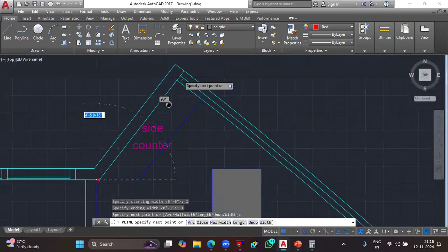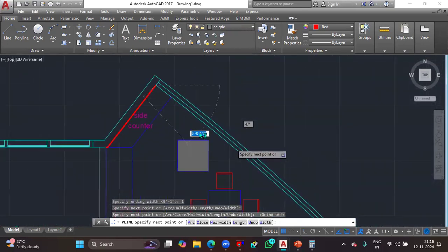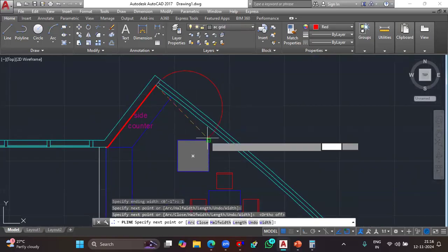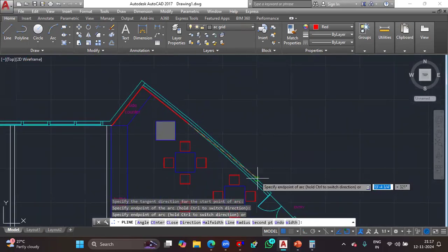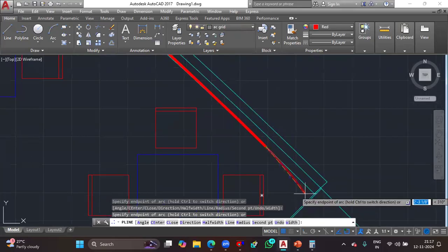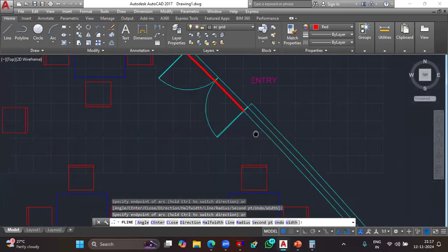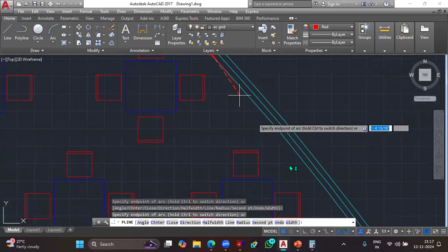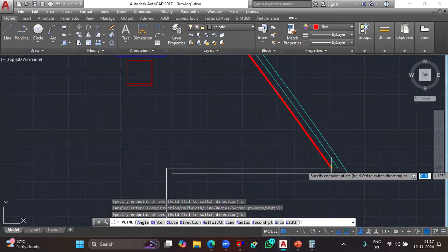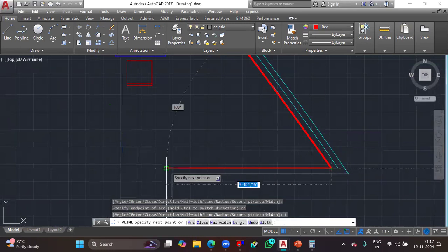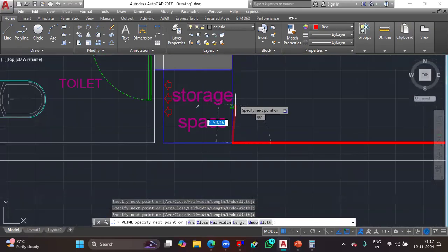Start from here, turn off the F8. It should still be helpful. The same thing that we used to take out the area. Remember? Then arc, enter, D, enter. That's it. Drag it down according to your need. You don't need to worry about the exact picking of points. It's just for the grid ceiling aspect. Simply enclose the area with this line. After that, swap back again to the line option, which is the same line command. All right. So that's it.